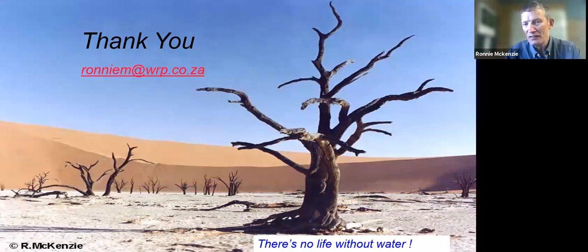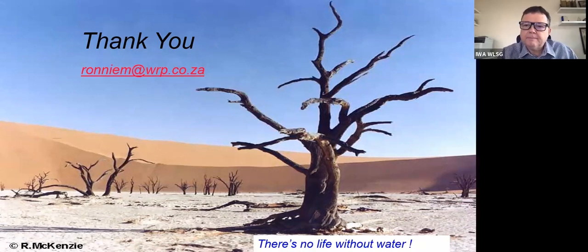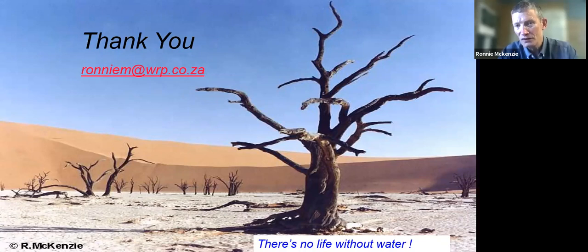What needs to be done after that is then move down to zones of, say, 10,000 connections where it makes sense, and to put in a smaller PRV controlling a smaller zone. The UK has the benefit of funding. They've got enough money to put in PRVs at smaller zones. In many of our zones, we didn't have that funding originally. So it's a question of where can you get most saving for the least amount of money.